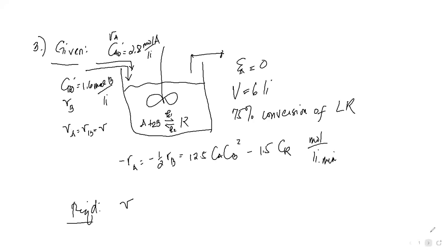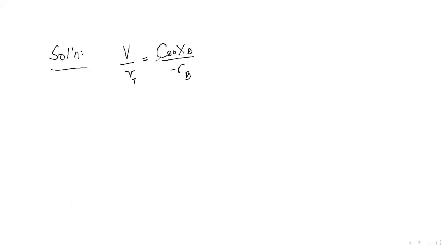But it's different than the V that is written here in the formula because this one considers the total volumetric flow rate of the streams that enters the MFR, not just of one stream. So this is V sub T. And I'm using component B here because the conversion that is stated is based on component B. So this is our working equation.